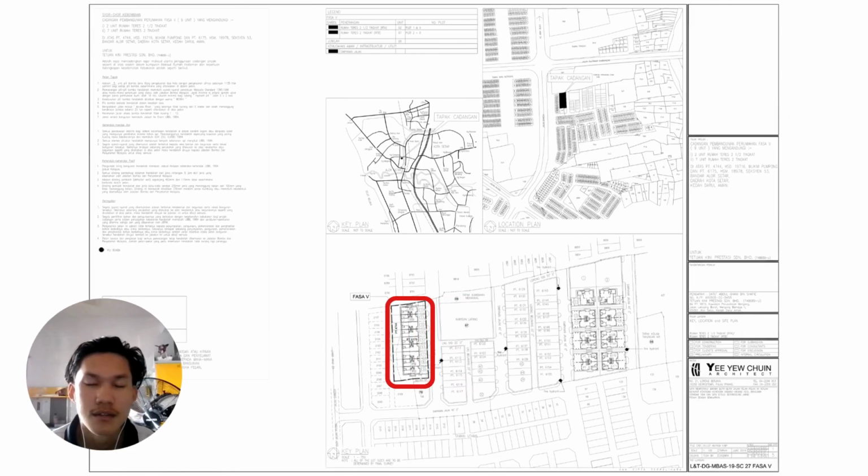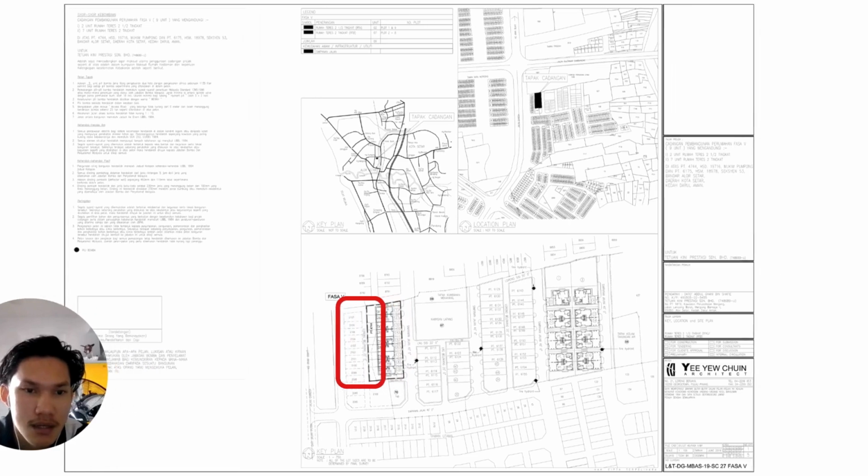Okay, next, the key location plan. So basically, the slide shows the key location of the terrace housing development. It indicates the orientation of the houses, access road, and the surrounding units. From an IBS perspective, this plan is important for planning the component delivery, stacking area, and the crane positioning, especially in a limited terrace housing site.